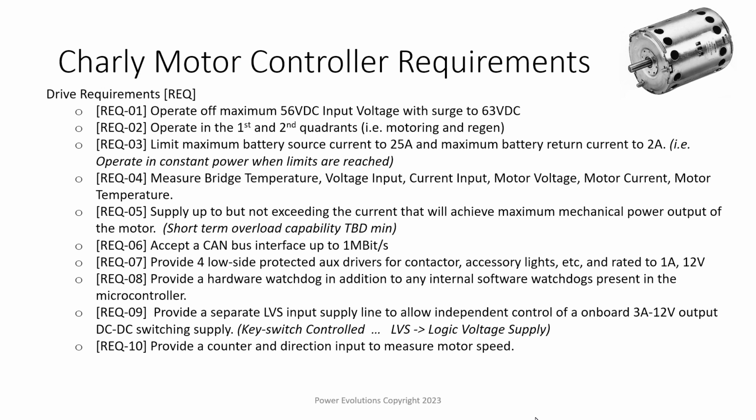Some of the other things we want with this motor controller is to be able to measure the bridge temperature. Bridge temperature is the MOSFET temperature. We also want to be looking at what the voltage and current inputs are to this controller. We want to know what the output voltage is, so the motor voltage, and what the current going out to the motor is, as well as motor temperature.